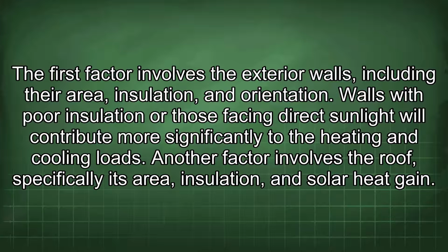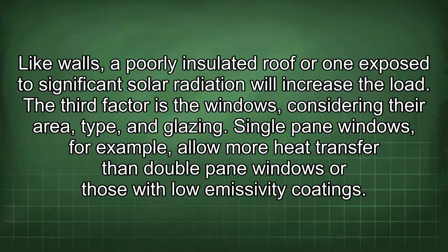Another factor involves the roof, specifically its area, insulation, and solar heat gain. Like walls, a poorly insulated roof or one exposed to significant solar radiation will increase the load. The third factor is the windows, considering their area, type, and glazing. Single-pane windows, for example, allow more heat transfer than double-pane windows or those with low emissivity coatings.